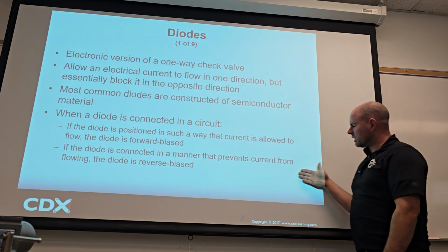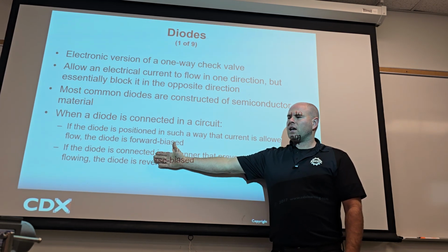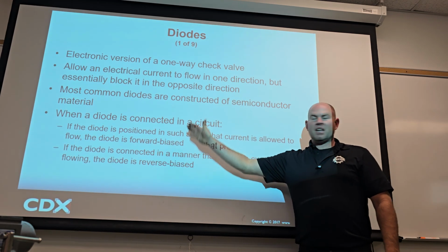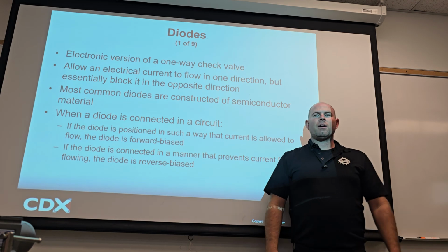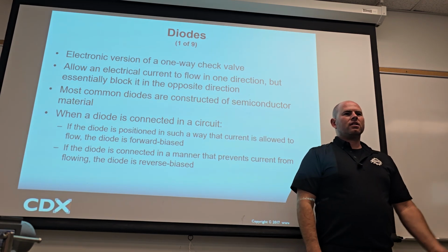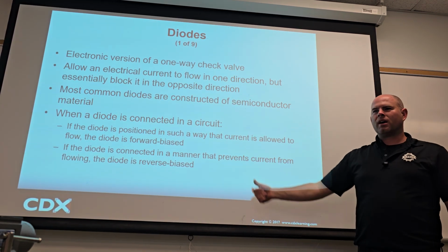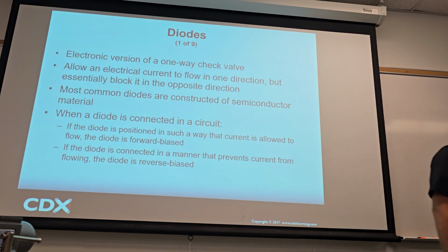If the circuit was supposed to allow voltage to go to the AC compressor clutch, but now it's backward, it won't allow any current. You're like, the AC blows warm ever since I did this other thing, and well, the diode's in backwards. These types of things. Cool. The good news is they have a little diagram so you can see which way they're supposed to face.